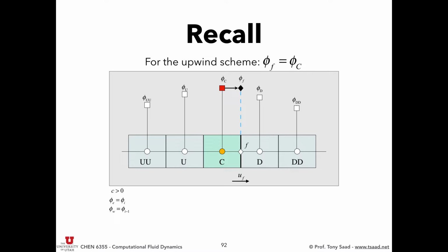And then you can construct your flux. So the right-hand side is negative the integral of the divergence of the flux, so that gives you flux at the east face minus flux at the west face, all multiplied by a negative sign, and you get this standard finite difference looking formulation for the upwind scheme. And also, if you reverse the velocities, just to make things clear for you, the east value would become the upwind value, which is this guy, and the west value would become the upwind value, so it would be phi i, and then you construct the flux that way.